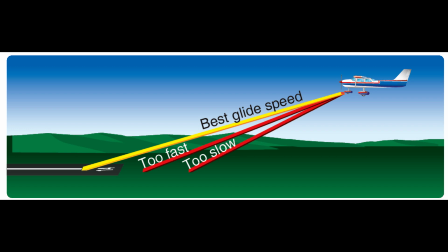Three elements in gliding turns that tend to force the nose down and increase glide speed are: 1. Decrease in lift due to the direction of the lifting force. 2. Excessive rudder inputs as a result of reduced flight control pressures. 3. The normal stability and inherent characteristics of the airplane to nose down with the power off.